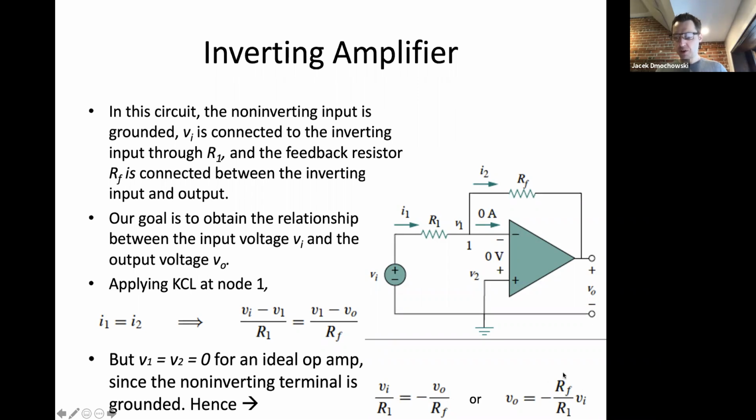And if we want to triple it, we will need to make it 3 times the size, and so forth. So this is the critical part, that we can use the op amp with whatever feedback resistance we want, and we can tune that value to achieve a desirable voltage.